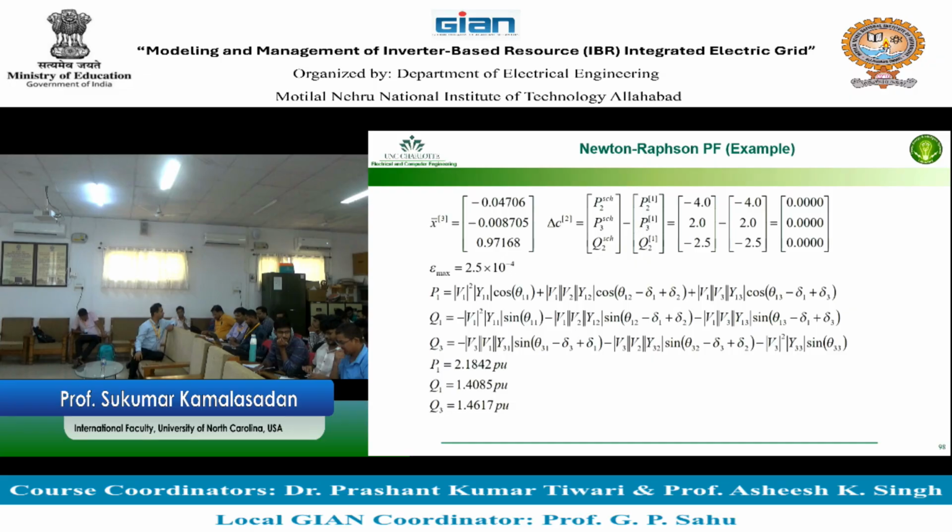So 2400 angle 0, 120, we wrote, right? Instead of 2400, it should be 2400 multiplied by 0.97, whatever the voltage is. For the same system we have to put it. For that 2%, you put 0.97. Let's assume 0.97, so you multiply 0.97 by 2400.